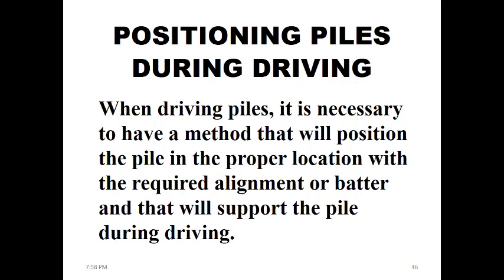So make sure that you understand how you have to choose it. Well, when we have to drive the piles, we have to make sure that these are positioned properly, because as I mentioned before, if something goes wrong, you wouldn't be able to pull it out and start again. Think of, again, nails. If you didn't position it properly and it goes under angle, you may decide to pull it with pliers and just reposition it and drive again, right? That wouldn't be the case with these piles. So you have to make sure that it's properly positioned right from the beginning.